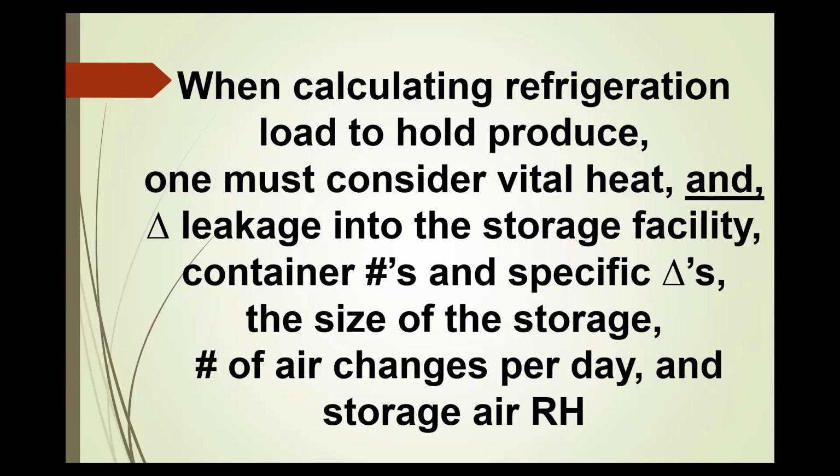When calculating refrigeration load to hold produce, one must consider vital heat and heat leakage into the storage facility, container numbers and their specific heats, the size of the storage, the number of air changes per day, and the storage air relative humidity.